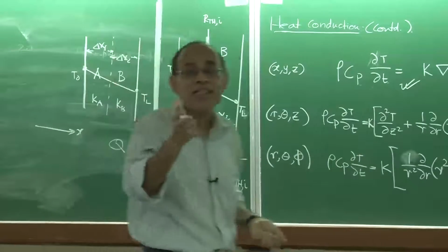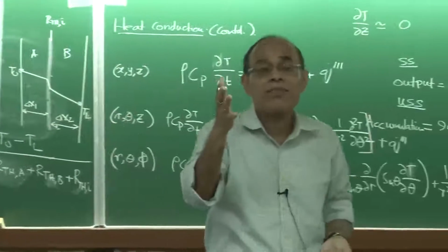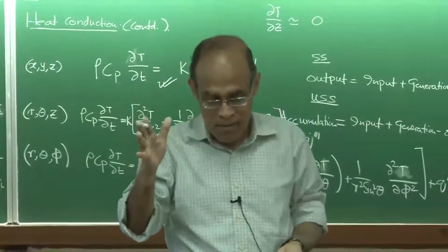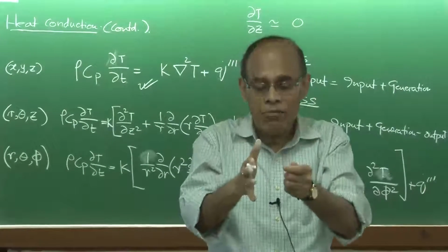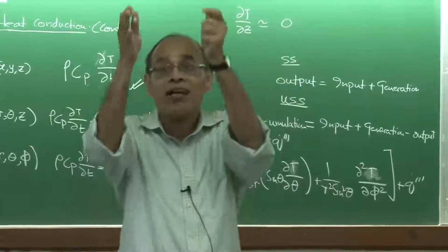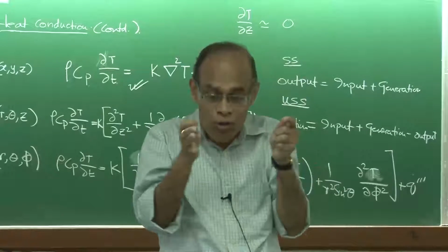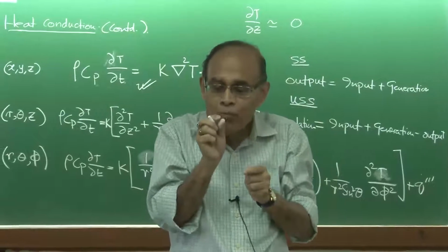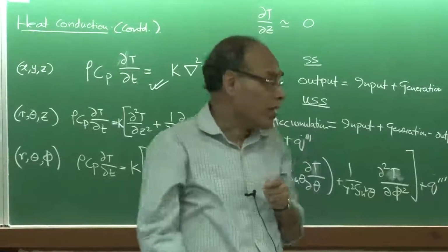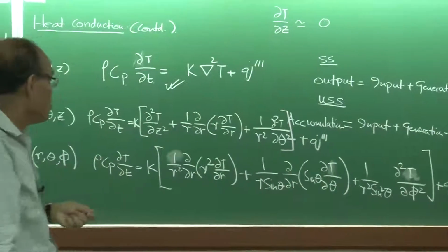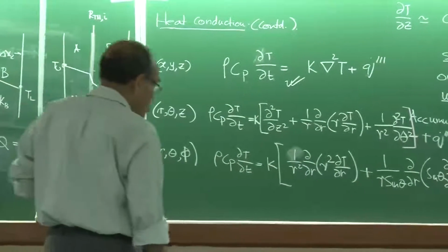Even in continuous casting, for example, the first problem that I discussed about the film flow and momentum balance in one dimension, you remember that I had a moving strand and a stationary mold, and between the two, a very small space, maybe less than a millimeter, which is occupied by the downflowing film of mold powders. Okay?